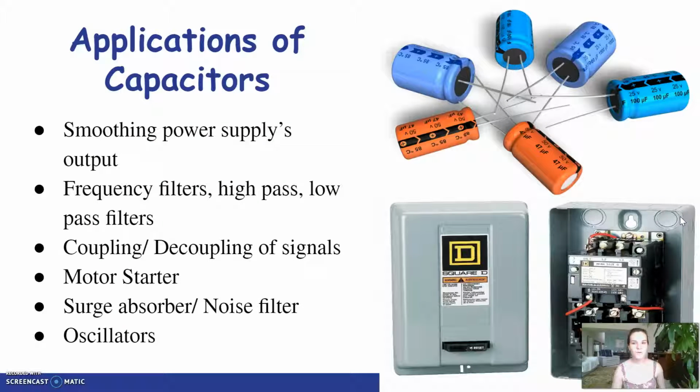You can use capacitors in smoothing power supply outputs, frequency filters, high pass, low pass filters, coupling or decoupling signals, motor starters like in your cars, and then surge absorbers and oscillators.